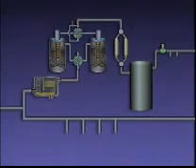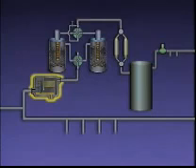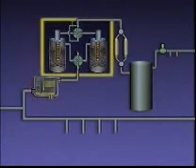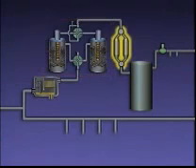This function is carried out by an oil separator. The oil that is removed collects in the bottom of the separator and is often drained to a waste system. A desiccant dryer removes moisture that may be present in the air. Filters remove any solid impurities that may be present.